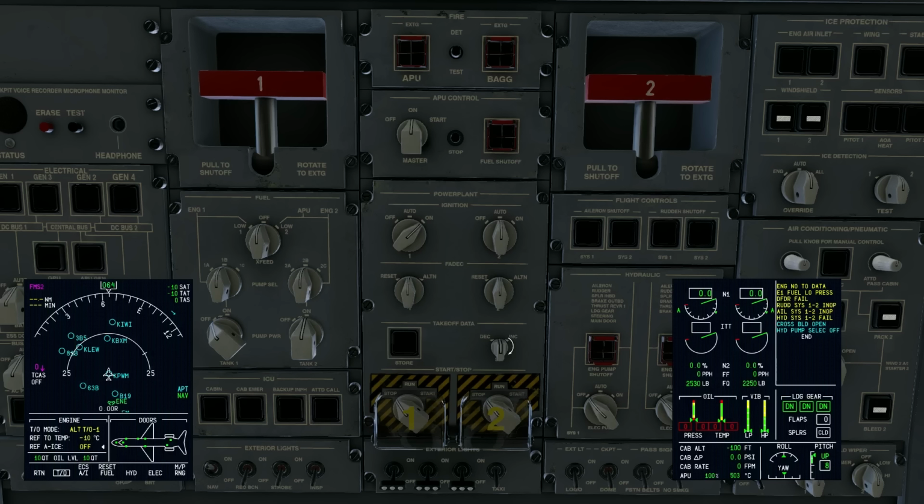Because you can imagine, if the FADEC thinks we're going to make 92% power, but by stealing that air from the compressor we can only get to 88, well, now we have a mismatch, and that's going to make the FADEC very angry. We're not producing the power expected, and problems start occurring. So instead, we tell it, hey, expect anti-ice, and then it's going to do calculations to figure out how much performance loss that anti-ice is going to give it.